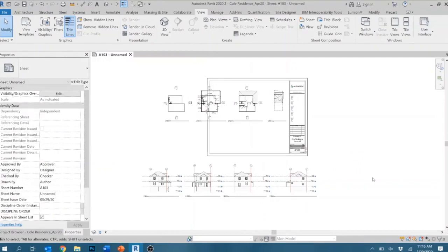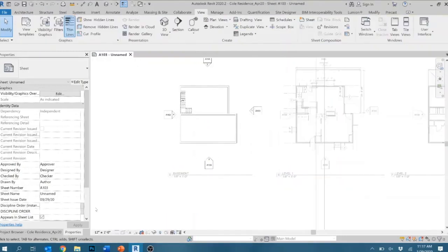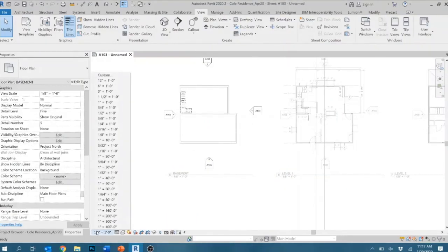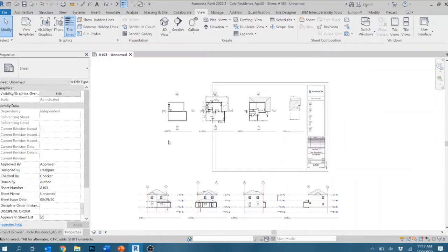I've created elevations and plans at a 1/8 scale. That means I've double-clicked in the viewport, selected the bottom left button on our horizontal, and have selected 1/8 from the menu. These still aren't going to fit on my sheet, so instead of 1 sheet, let's do 2.